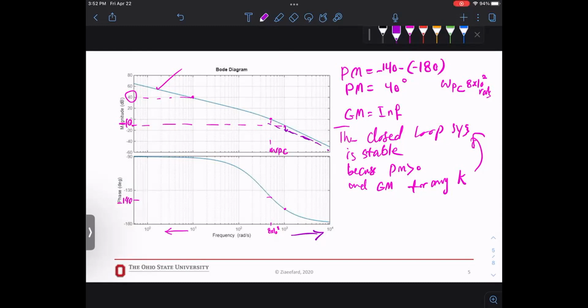50% chance of being right. So a lag controller has a pole close to the imaginary axis, right? That's good. It acts like an integrator, so it's good for getting rid of the steady state error. A lead controller makes your system more stable, has a pole farther out, adds damping, and also helps phase margin. That's basically the advantage of designing a lead.